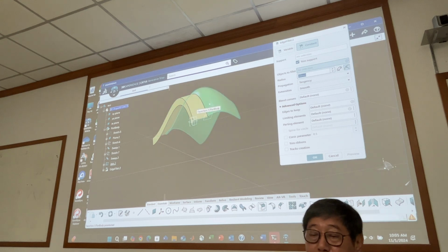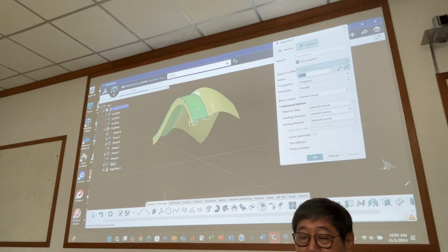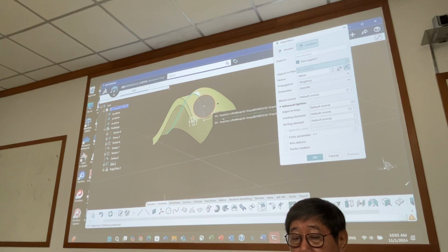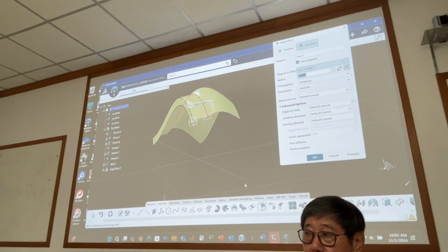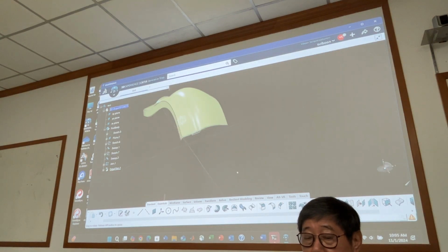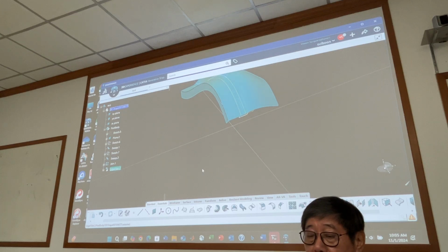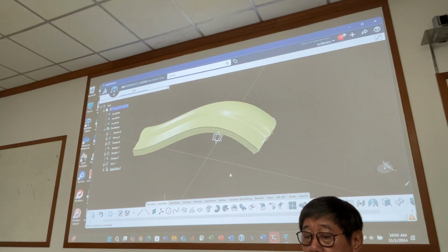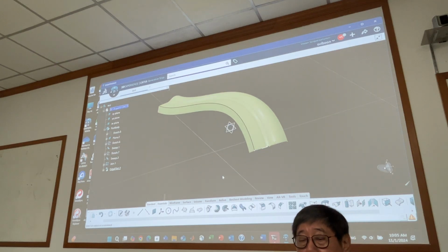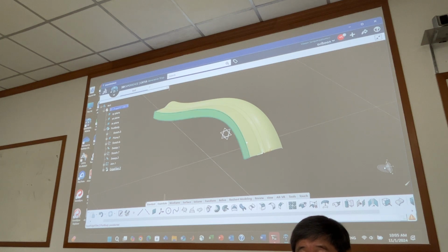See, if you see the surface, right? You can use the alternate key and select this one. Edge, you see? Edge. Right? And preview this one, 30, it's okay. See, this one. And now the edge is all of them. Combine all of them, right? See, this one. See? Okay. You can fillet this one as well if you want.